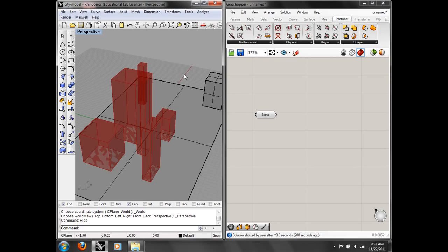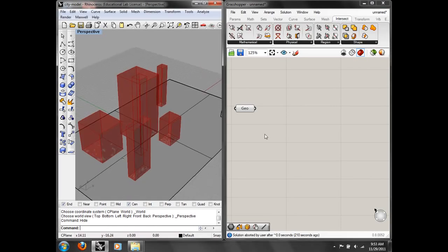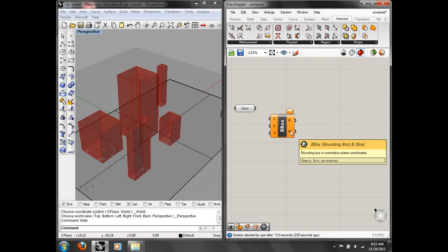If you had something that was crazy or warped or had an odd shape, that might be hard to do. But there's actually a pretty easy way to find the volume of anything, and that's to do a bounding box. And we saw one of these when we did that morph thing, where we did the two different kinds of things that we morphed around that sort of tower. A bounding box just creates an envelope around some object. And if we measure the bounding box geometry, we can find that data really, really easily, instead of having to actually look at all the points in the object.